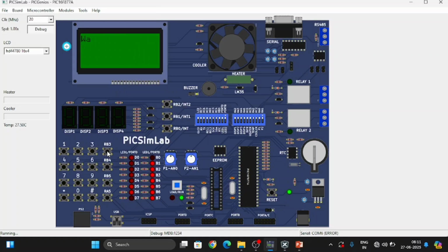Now let me navigate through the programs. I'm going to use heavy. Now I'm long pressing the switch 4. And as a water level, I'm going to choose high. Okay, now I'm long pressing the switch 4. Okay, now it is asking to press switch 5 to start or stop. Now let me press switch 5 to start my program. Okay, now it's showing program heavy and the program has started.